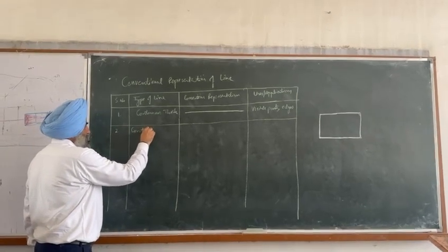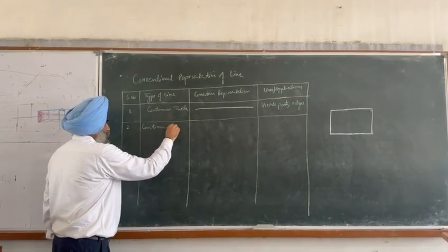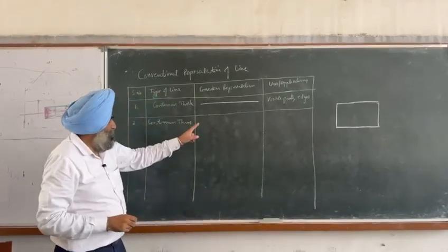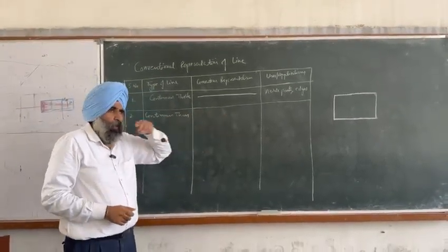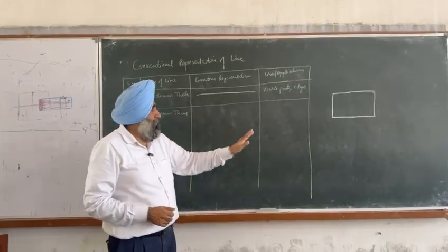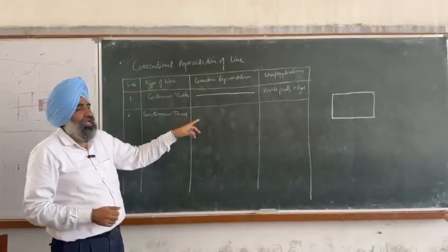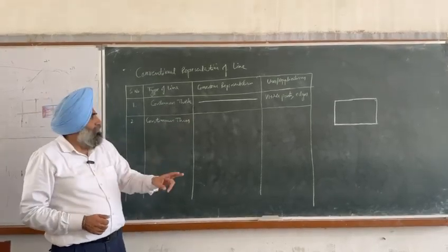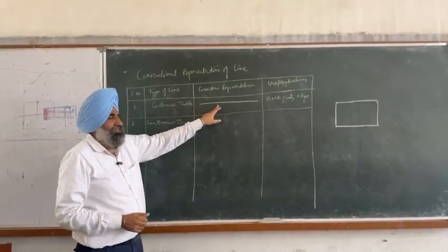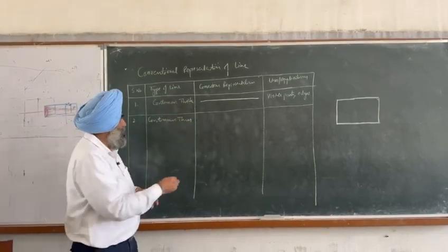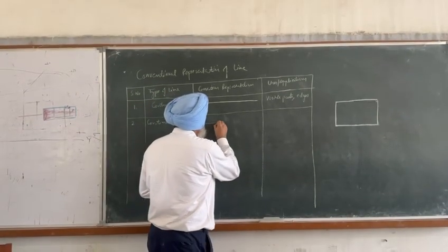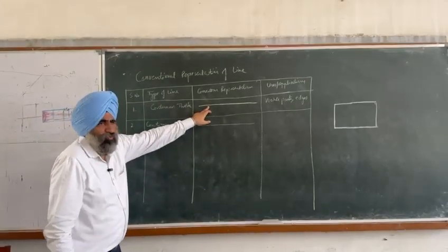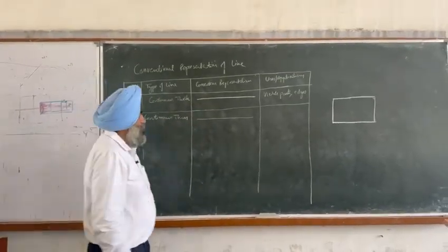continuous thin. If you are having two types of pencil, again HB and H, but basically there are 18 types of pencil, which we have already discussed in the last class. If you are having only two pencils, HB and H, make use of the HB pencil for this continuous thick line, and for continuous thin, make use of the H pencil. So this is lighter than this one. So this is continuous thin.